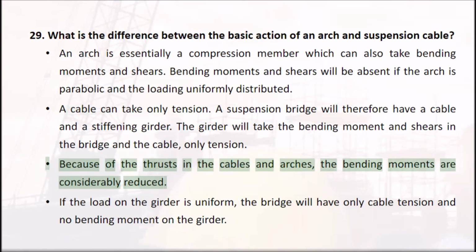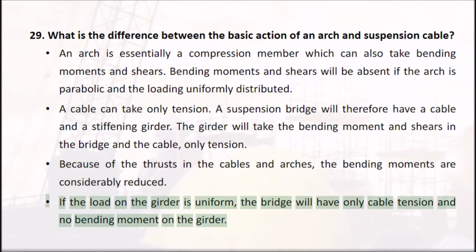Because of the thrusts in the cables and arches, the bending moments are considerably reduced. If the load on the girder is uniform, the bridge will have only cable tension and no bending moment on the girder.